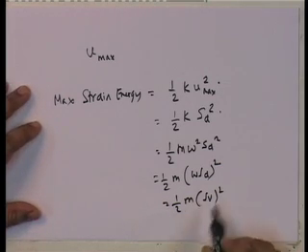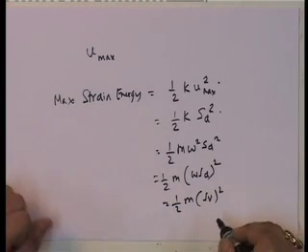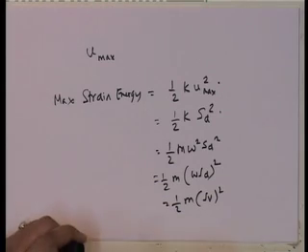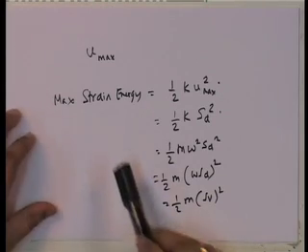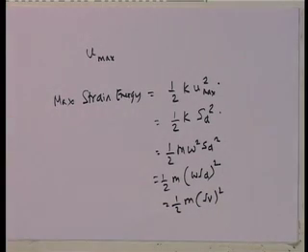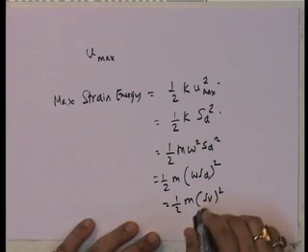And so, now what are the units of S v? Obviously, velocity. What is the maximum strain energy? It is equal to half m into the pseudo velocity spectra squared. So, think about it. This looks like maximum strain energy is equal to maximum kinetic energy. It looks like a kinetic energy term, does it not? Excepting that it is not kinetic energy, because it is a pseudo velocity spectrum.